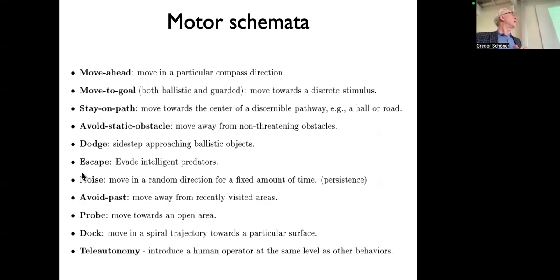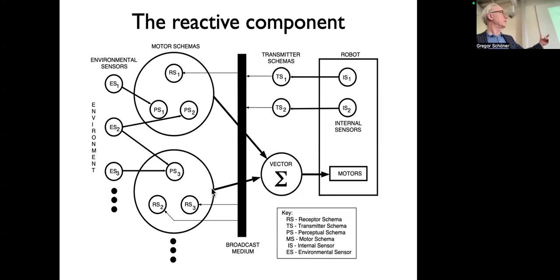And it's the architecture that decides, this is not specified here, but we'll look at that in more detail in a moment, that only one of those motor behaviors might be on, or two might be on at the same time. The priority function would say, if any obstacle behavior gets some input, then that's going to be the module that's active, and everything else is not active. Not active meaning not sending anything here. And that's how you could organize across these different behaviors, and would have flexibility, would not just do averaging all the time.